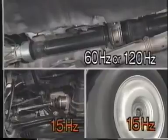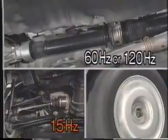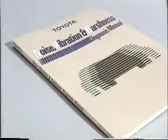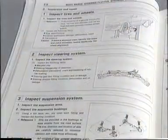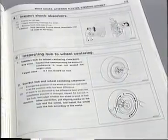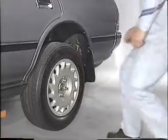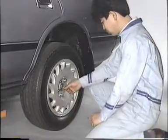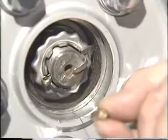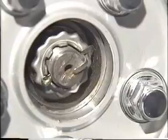Now, we will return to troubleshooting the problem of vibration at 15 Hertz. We will start with inspecting the tires, because tires often cause body shake at high speeds. We will refer to the NVH diagnosis manual as we inspect the tires. Before we begin the inspection of the tires, we must check the tires and wheels visually, the steering linkage, the suspension system, and other related components. If everything is normal, we check the clearance between each hub and wheel. The standard clearance is less than 0.1 millimeter.